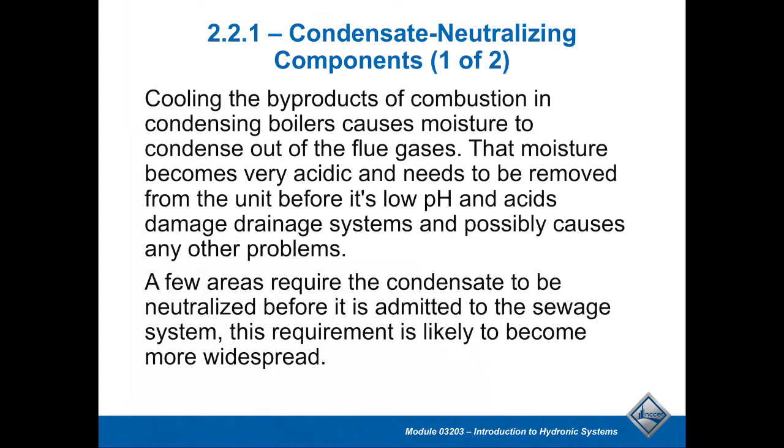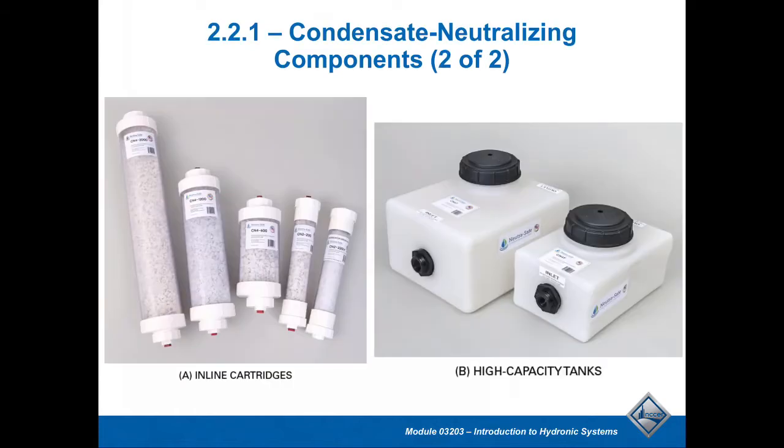The low pH correlates to an acidic nature. We have to watch, if a person had cast iron drainage systems or copper drainage systems, those systems would be eaten away. PVC would be fine, plastic piping would be fine, but any of the metals would be deteriorated. So in some cases, they will require you to have some sort of a neutralizer.